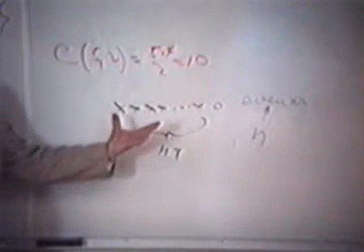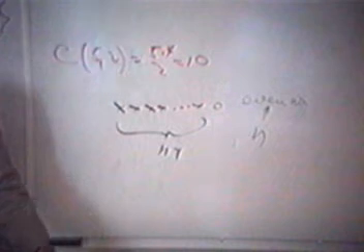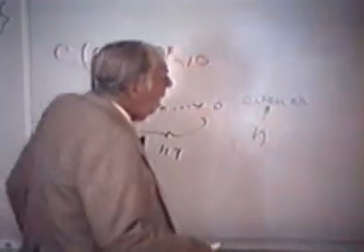So we have to look at the question of what the probability of errors is. Now if I have a very short message and the probability is low, the chance of a double error is very, very low. If I make a very long message, the probability of 2 errors is kind of high, right? On the other hand, I'm getting more for the extra 1 bit that I'm having to send, which is wasted capacity. It's channel capacity, but you're wasting it for reliability. So you want long ones to cut down the redundancy of the extra bit. You want short ones for reliability. So you want the probabilities. So you say to yourself, well, that's not hard to get. We know a little bit about probability. We don't need to know much.